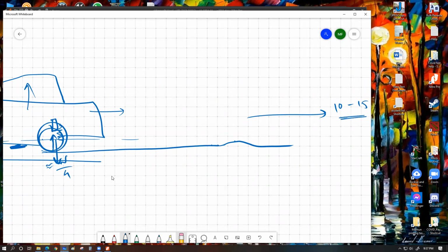Now, if this delay was not there, what would have happened? Let's say we only installed springs over here. We did not install any shock absorber or any kind of oil valve mechanism. In that case, as the car goes above the bump, this vibration will be transferred to the whole car. All the passengers and the luggage are going to experience that jump, and this jump is going to keep on happening for a significant duration, because the energy loss would happen very slowly while the entire car body has to undergo vibration. This is exactly what we want to prevent.